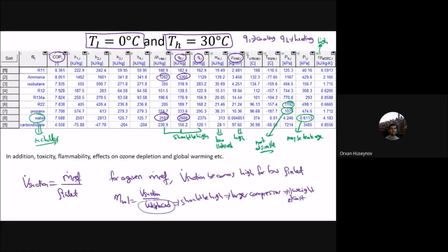And if its temperature doesn't change enough, it means that we don't need much cooling for water here. Therefore this CP value should be very high, such that we have good heat transfer without any significant temperature change in the working fluid.